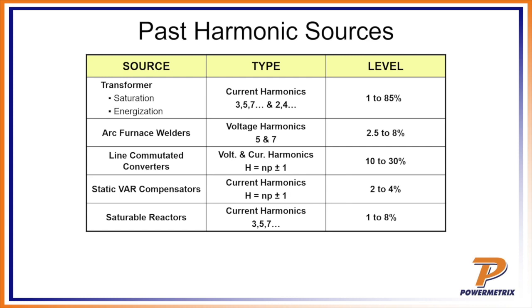He's like, "Well, yeah, I do." I said, "Well, where are you hooking up the auxiliary power on your Powermaster?" "Well, I'm hooking up right at the meter." I'm like, "Now wait a minute, let's stop. That's on the secondary side of those PTs. What are those PTs rated for?" "Well, they're 100 VA PTs." "Well, no, sorry, Mr. Customer, that Powermaster will probably draw upwards of about 1,000 VA.